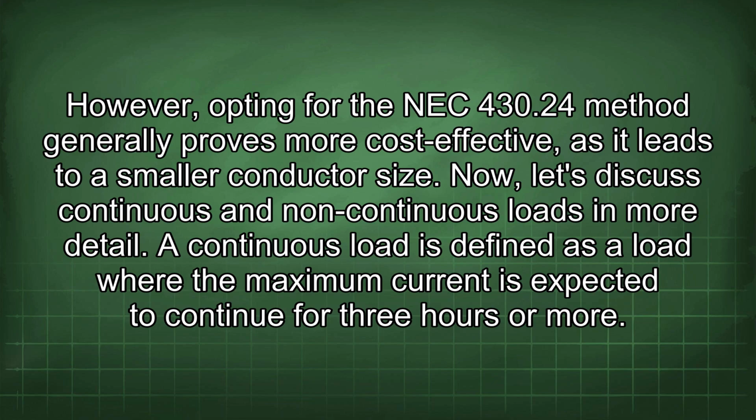However, opting for the NEC 430.24 method generally proves more cost-effective, as it leads to a smaller conductor size. Now let's discuss continuous and non-continuous loads in more detail.